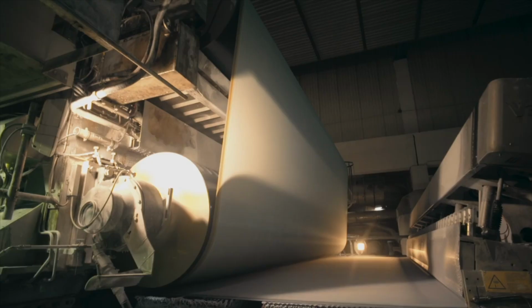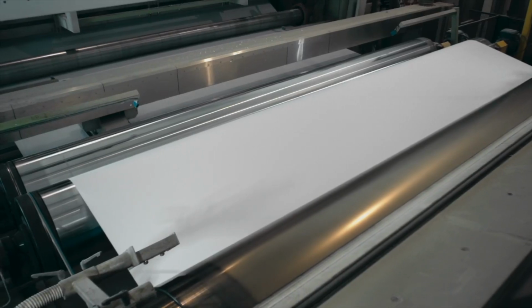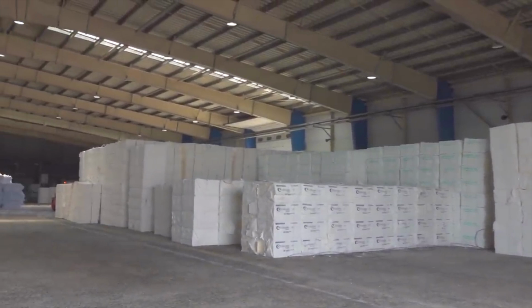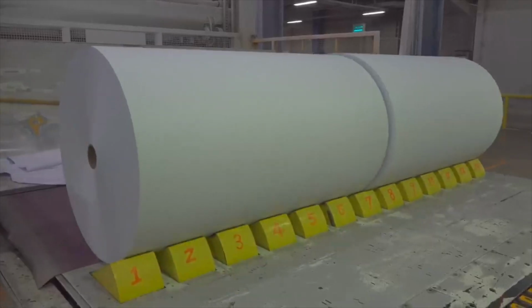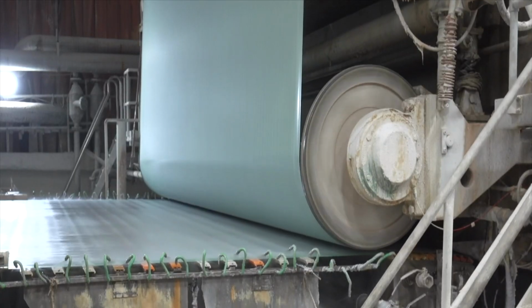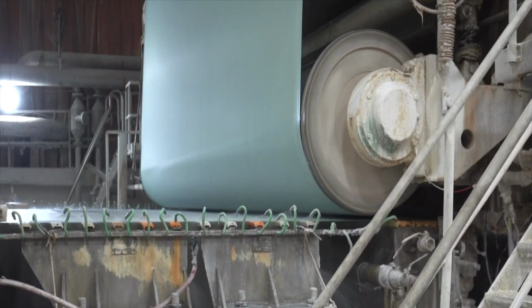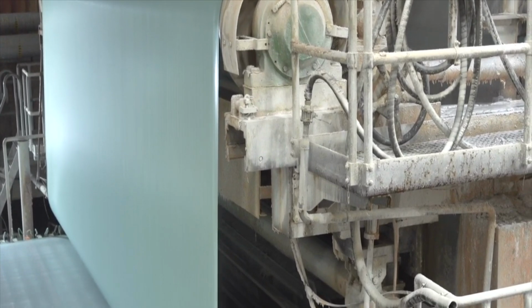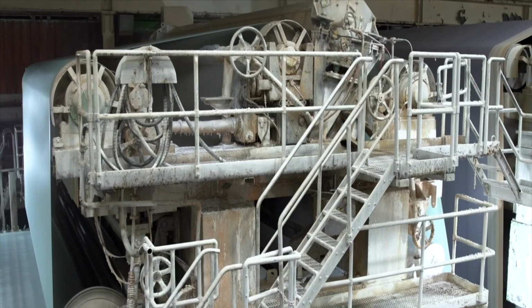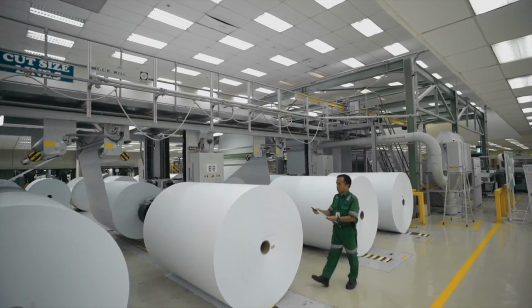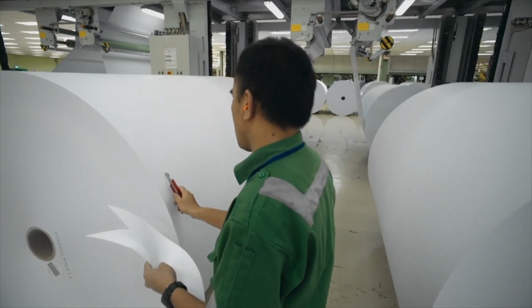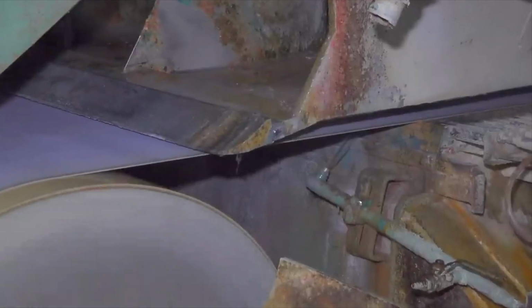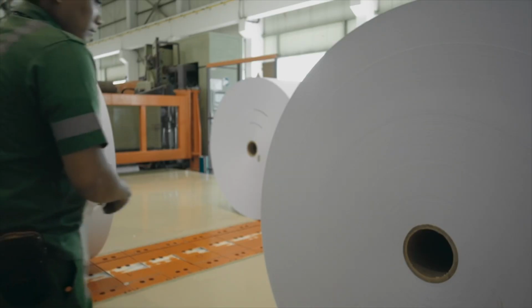The pressed paper sheet then enters the drying stage, where the objective is to completely eliminate any remaining moisture before it is wound onto master rolls. This drying process transforms what is still a damp paper web into finished dry paper ready for cutting and processing. Paper drying relies on the application of intense heat from steam-heated dryer cylinders and rolls. As the pressed sheet travels around these hot metal drums, the heat evaporates the remaining water in the sheet through contact and convection until the paper emerges dry. Monitoring moisture levels through the drying stage allows for exact drying tailored to the paper's thickness and specific water content. The drying stage's efficient water evaporation yields the final paper product ready for finishing steps.